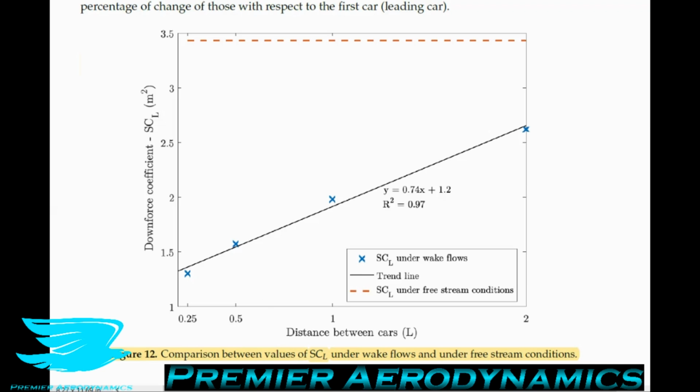So in figure 12, the effect of the distance of the downstream car from the upstream car on the lift area is very clear, and the relationship is actually linear. So in effect, the further downstream you go, the more lift the trailing car will produce. What's more, even at 2 car lengths downstream, the lift area is still only 2.5, whereas just one car in a free stream flow yields a lift area of 3.5. So even at 2 car lengths downstream, you've dropped the lift area by about 30%.